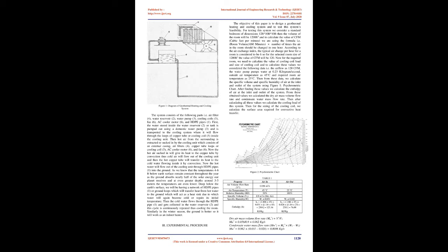The heat transfer rate between the geothermal heating and cooling system and Earth depends upon the conductivity of soil, the thermal inertia of soil along with many other parameters like water holding capacity of the soil, and the depth. There is some efficiency advantage of geothermal heating and cooling system over evaporative air cooler and air conditioning system, as geothermal heating systems can extract up to 6 times the heat energy they use in electrical energy.